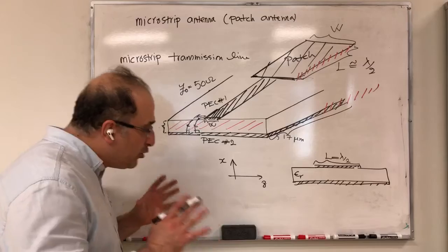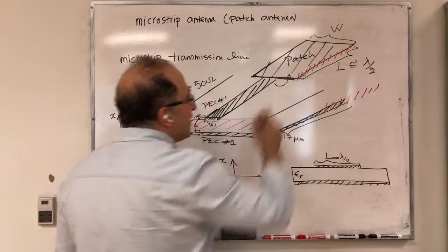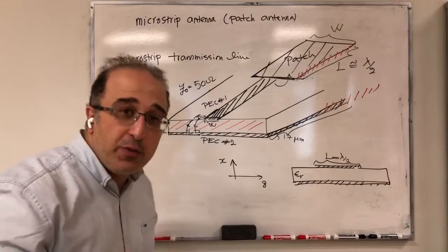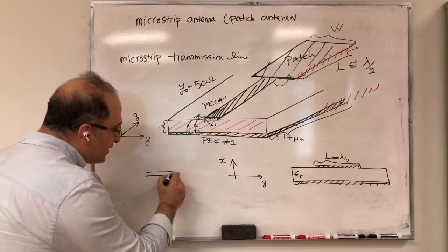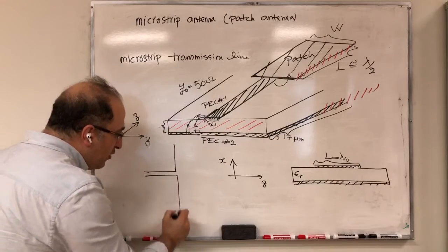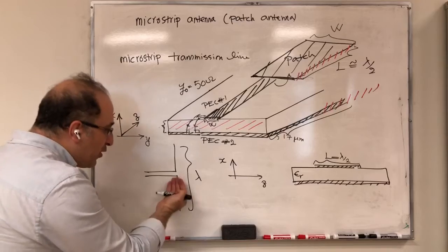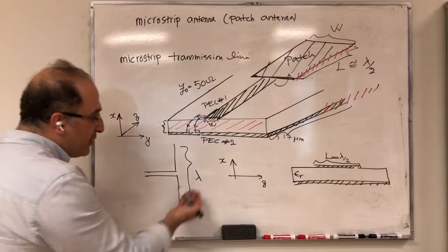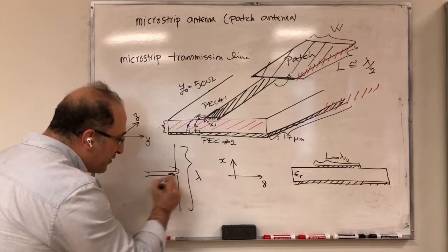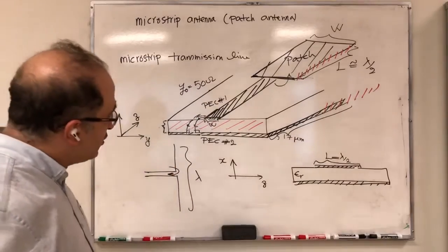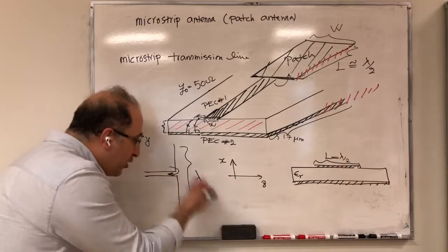Now assume that I'll do my job correctly and I can give power to this antenna, because it is very important to be able to give power. Remember, if the dipole antenna was one complete wavelength, things were okay in terms of complete wavelengths. The problem is the energy is going to reflect back almost completely, so you cannot give the energy.